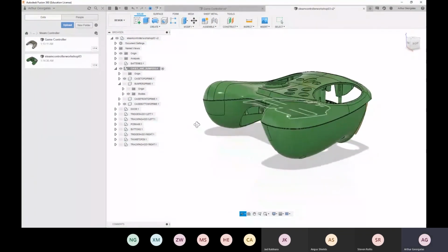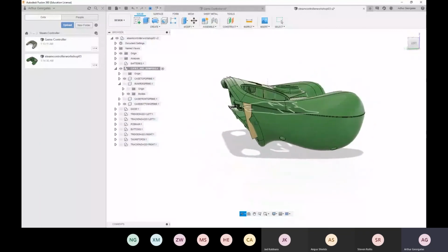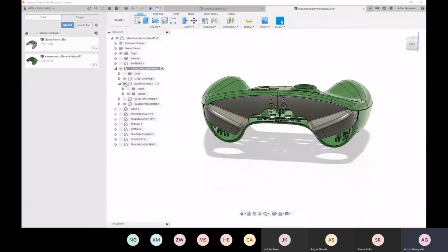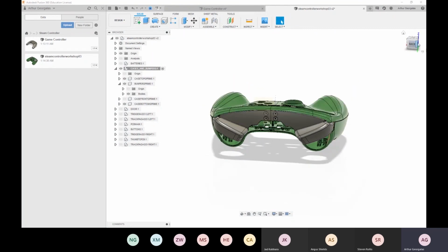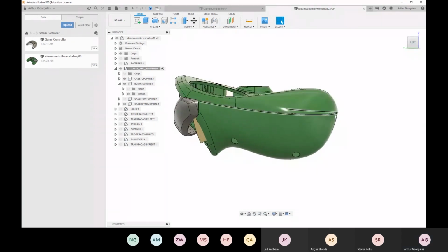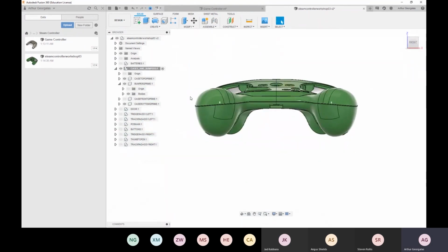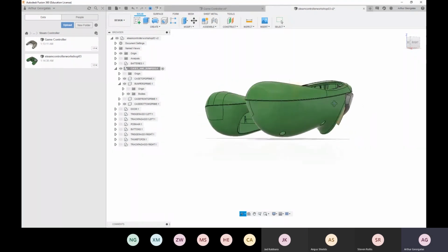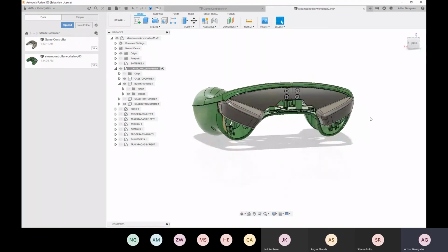And like I said, coming back to the brief, talking about splitting a surface with a, what was the wording on that? It was a non-planar something. Splitting a body with a non-planar subdivided surface. So what that pretty much means is, from this side, it looks like it's split with a single line at an angle, but then when we go from the front, we can see that it goes down, it comes up, and it's kind of like this type of 3D split.